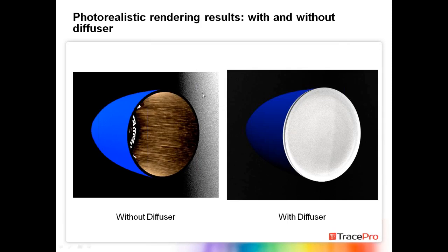We also have, included with TracePro, an IES LDT analysis utility that would allow us to use that IES file to create custom lighting reports. And here are just a few samples of some of the graphs that are possible. These are some of the default reports that are already predefined, but we also have the ability to create custom reports where you can drag the analysis tools that you want to see into the report and then customize it for your own application.